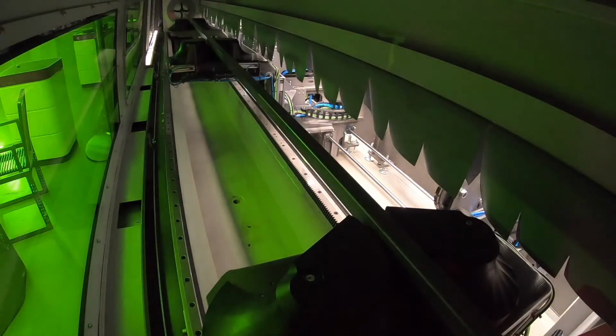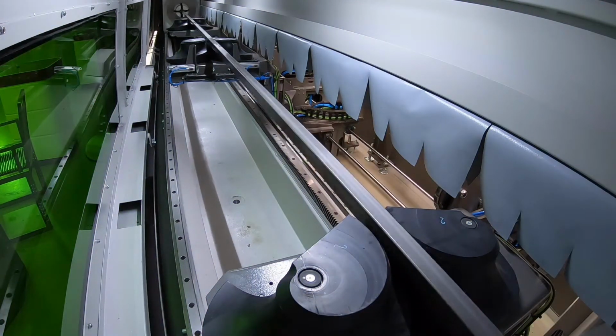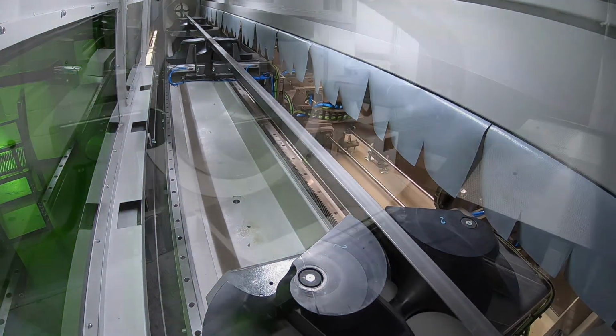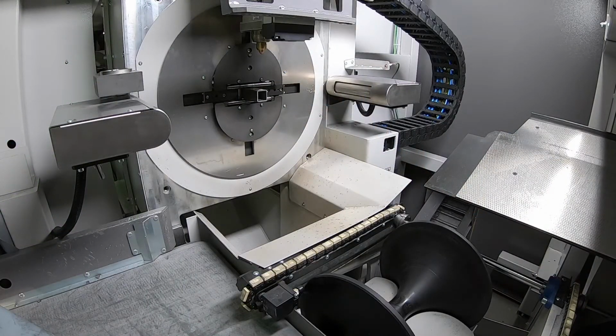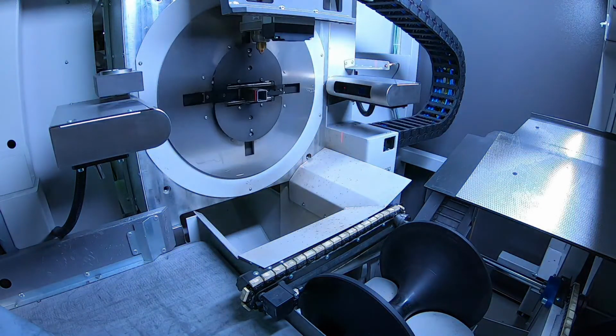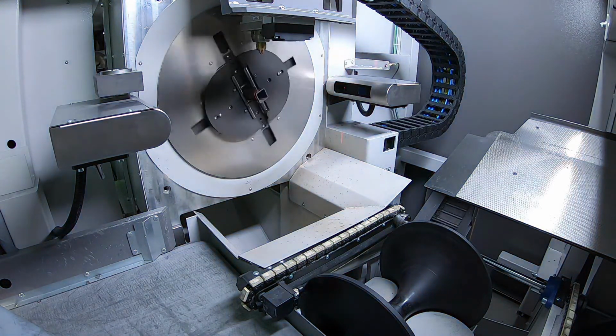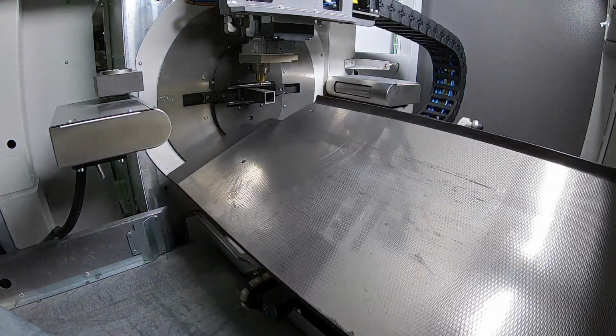Now we're waiting for our tube inside. Once the tube will reach the mandrel number 2, it will be inside the chuck. The chuck will close and we will see a red light. This red light is called weld seam camera, like you see. It will detect the weld seam on the tube, and according to the weld position, we will have all the holes and all the cuttings well positioned in our tube.